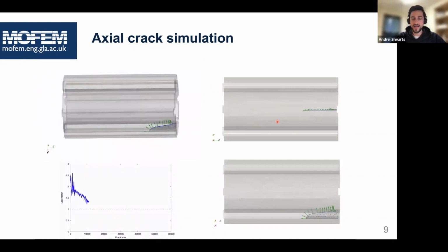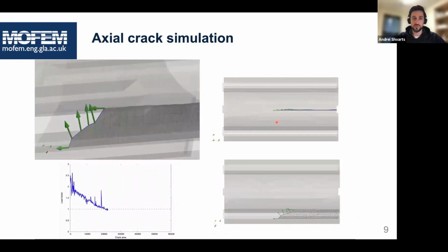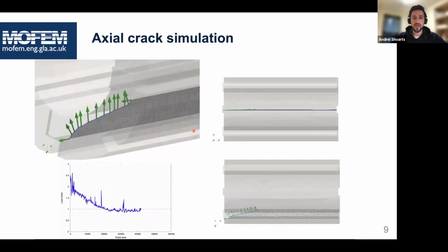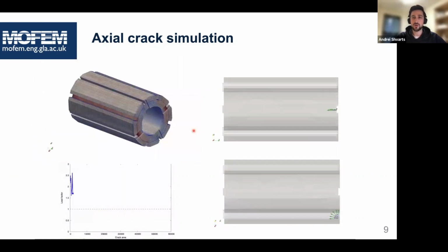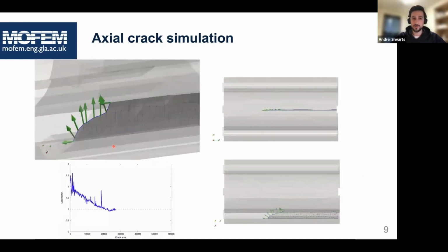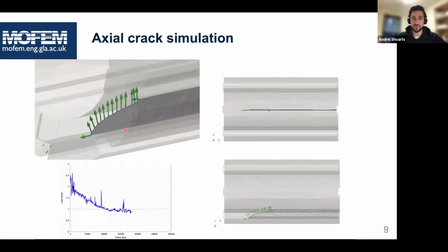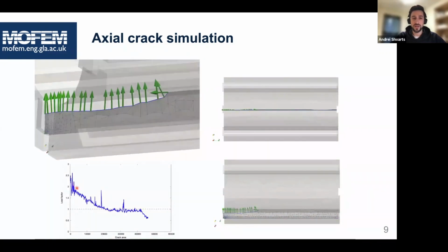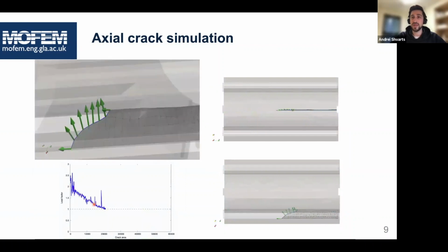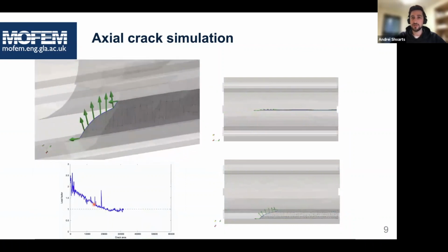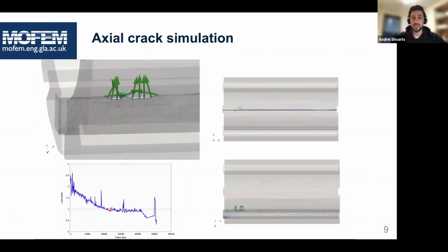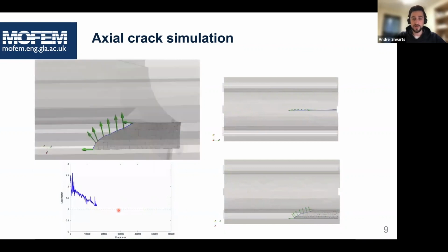Here you can see it from different angles, and the propagation of this crack, which is in fact very similar to the one you saw in the video on the previous slide. The reason for this crack is this complex distribution of stresses that we discussed. And in addition to just visually understanding the path of the crack, we can look into the load factor. The value of the load which is needed for the crack to propagate for a given power plant and a given number of years of its operation. And based on that, the engineers can assess the safety of operation of power plants.